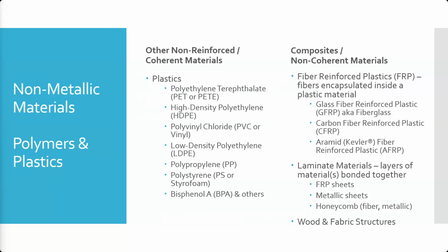That's what you're making when you're making a layup, or sorry, a single layer layup, I should say. They also don't have to be a mat. Like you've all used the woven mats, right? You can have a plastic where there's just fibers embedded in it. They basically take a canister with a bunch of loose fibers and drop it into the liquid plastic, whether it's melted plastic or an epoxy before it cures. Epoxy, once it cures, is a plastic, by the way. It's a form of plastic.